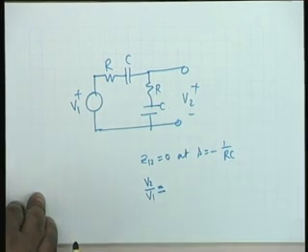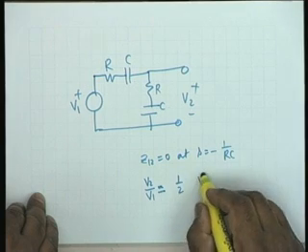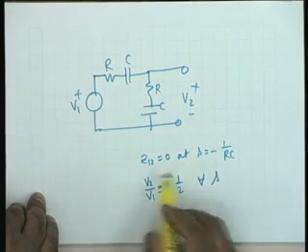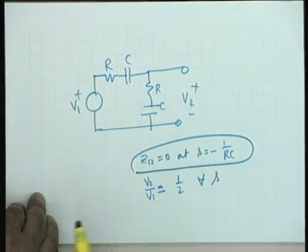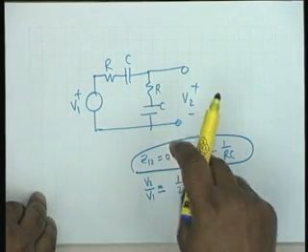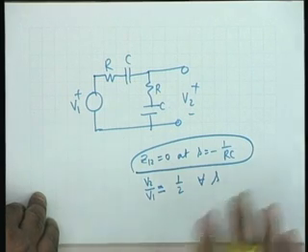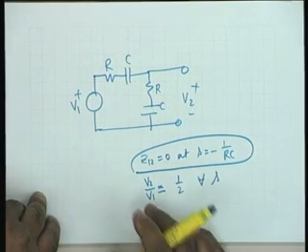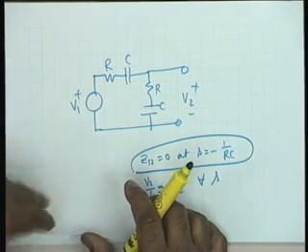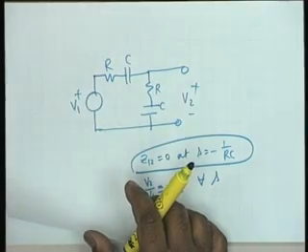It is equal to 1 or half at all s. Therefore, a 0 of Z12 is not necessarily shared by all other transfer functions, but generally it is so. Unless there is cancellation, generally it is so. So it suffices to consider in ordinary cases just Z12 or just Y12. Alright? Is the point clear?